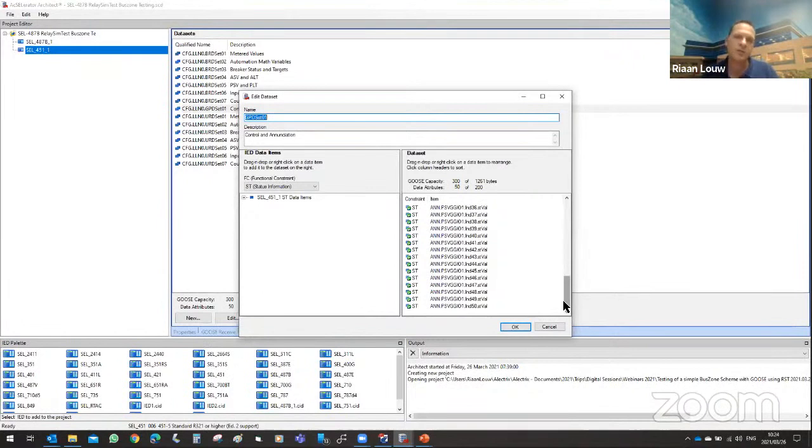So I can make that relation to say that my virtual signal, which is one signal, is replacing my input, which was another signal. Sure enough, you could have used the double bit statuses from the 61850. I've just gone this route, which is one way of doing it, but I've tried to make it as relatable as possible for a protection guy looking at an input and having to consider that that input is now being substituted with a virtual signal.